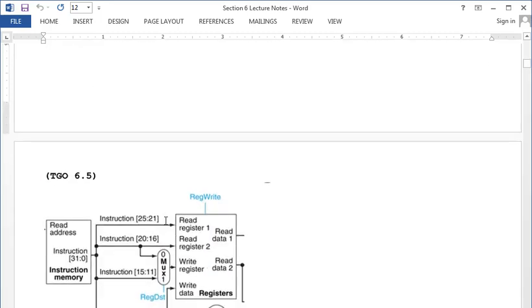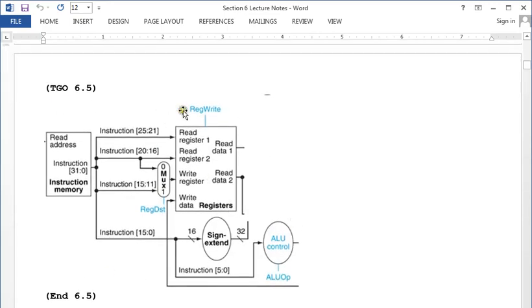Okay, so this is the drawing of the instruction decode stage. So we get the instruction memory out. The opcode goes to the controller. 25 to 21 goes to read register 1. That's RS. The 5-bit goes to the 5 to 32 decoder, gives me the value, and then reads it out. So these output values are 32 bits.